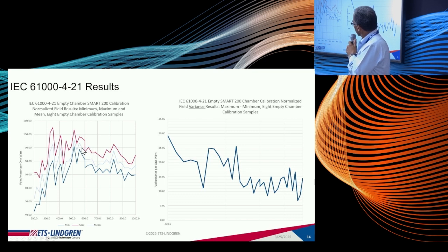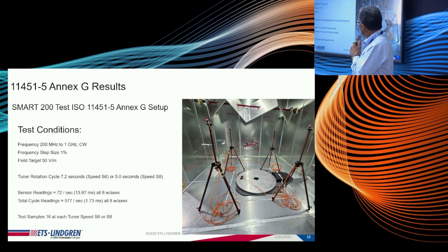The average of the maxes is the faint blue line, and then at the bottom in dark blue, we have the minimum of all the maxes. So we can see that in comparing the maximum measurements of all 8 probes, we can see how that maximum varies over those 8 probe positions using this IEC procedure. So fairly wide variation in the measured maximums with those 8 positions.